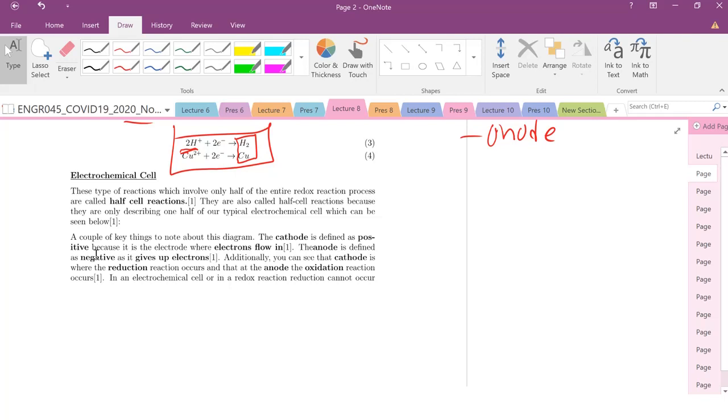You put them together. If there's some conducting fluid or material between them that is able to conduct electrons, due to the electronegativity difference, one material is grabbing electrons and pulling them away from the other material, and one material is giving up and losing electrons. And as you lose electrons, you lose material, you corrode. If you're gaining electrons and grabbing material, you're not corroding.